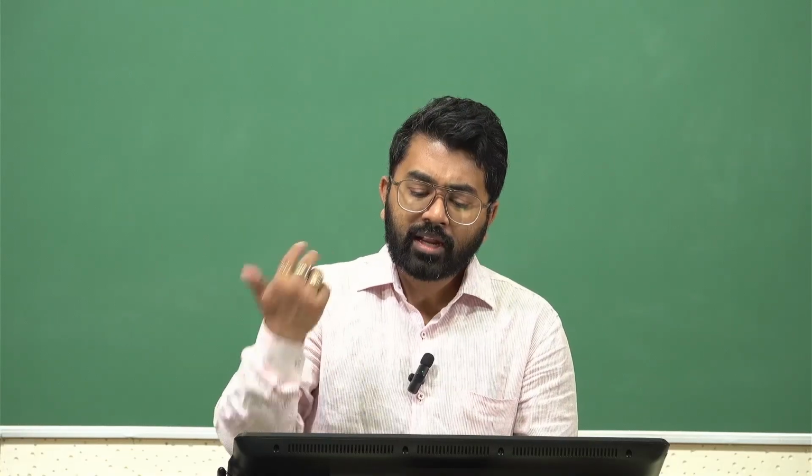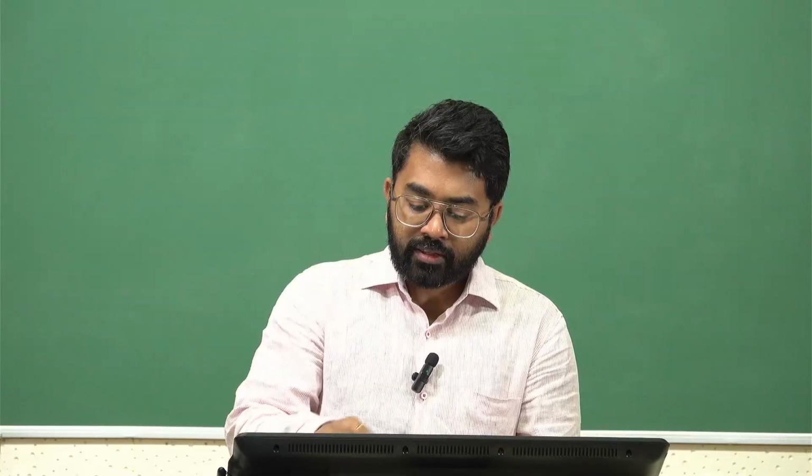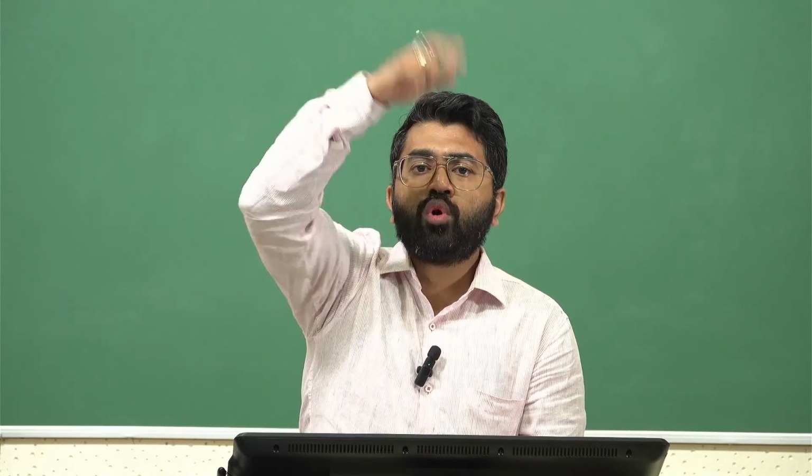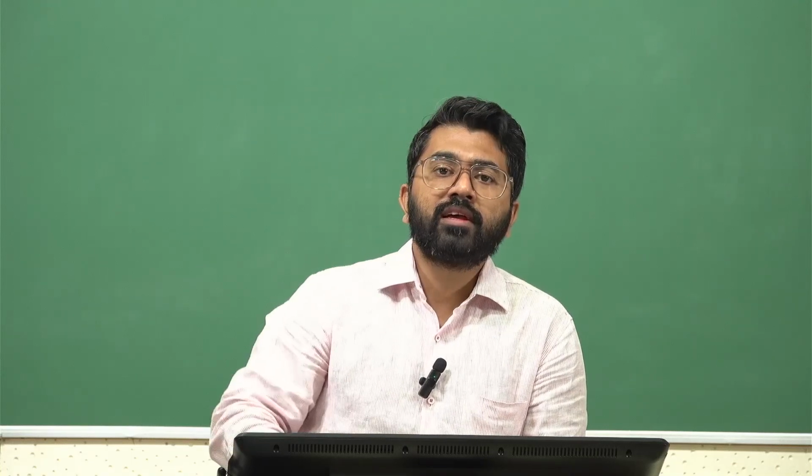On the right side you can see the stress strain plot, which is dynamically noted, and you can take this data out also. The red switch on the bottom next to the yellow is a kill switch. So if at some point the clamps go off limits, then you can hit the kill switch and the